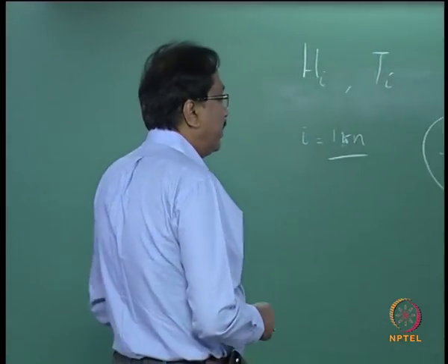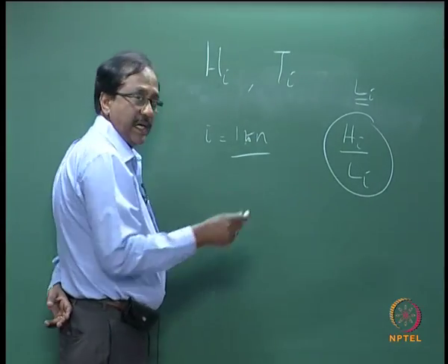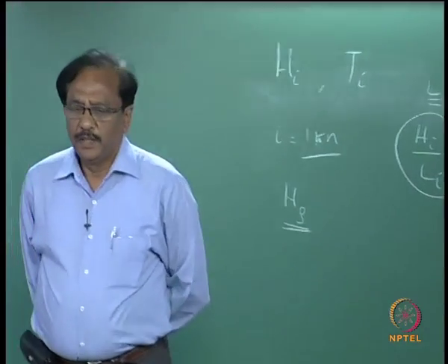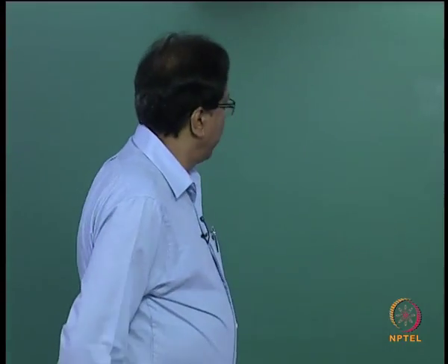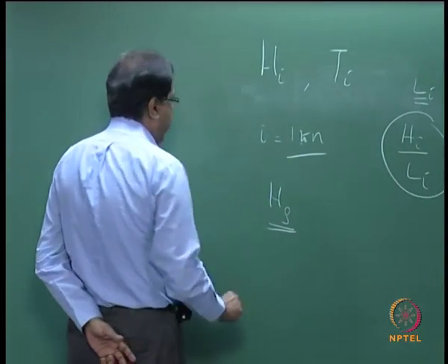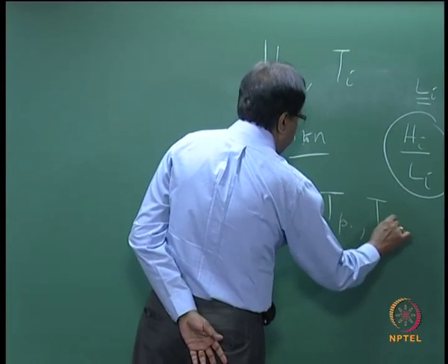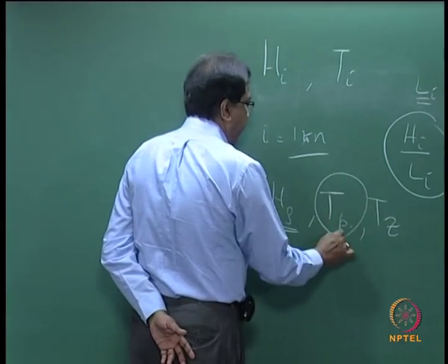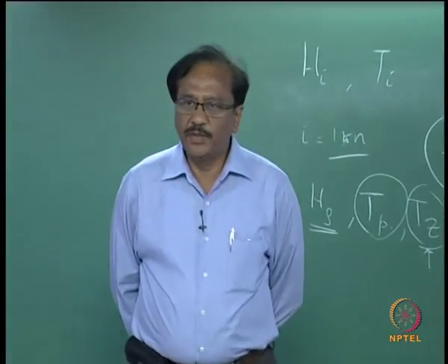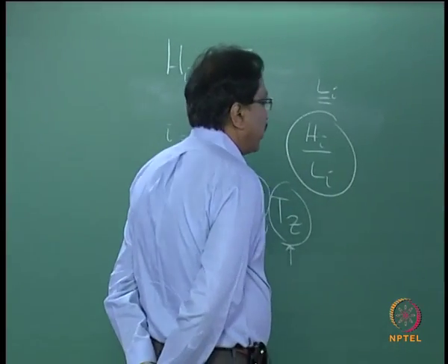We usually describe the general wave characteristics in a random wave. We normally use the significant wave height for representing the characteristics of a random wave, and the frequency is referred to as peak period or zero crossing period. I will come to this later, but as far as statistical analysis is concerned, we normally use what is called the zero crossing period or average zero crossing period.